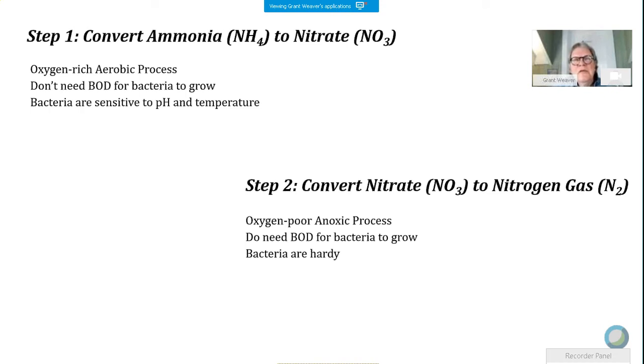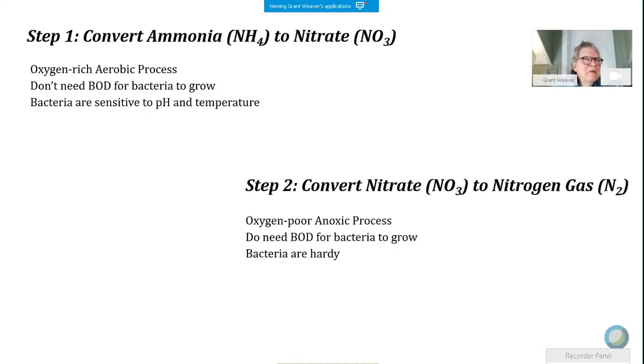Ammonia removal then is a great tool in that if you're removing ammonia, by default, you're removing BOD. So if at some point in that long, skinny tank, if that was your situation, you find ammonia is dropping down to a non-detect number, from that point to the end of the tank, whatever air you're putting in that tank is just bubbling through the tank. You're really done with your treatment.